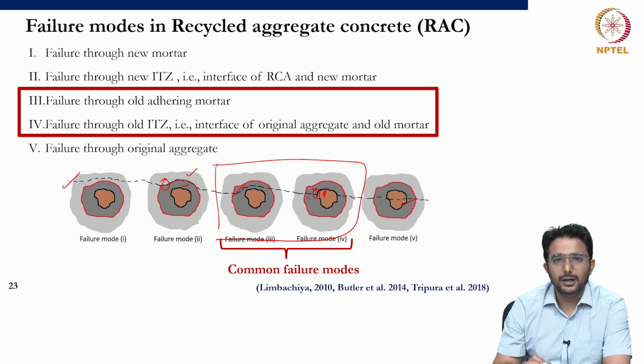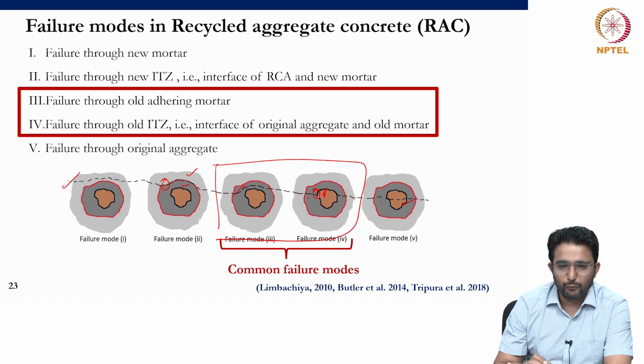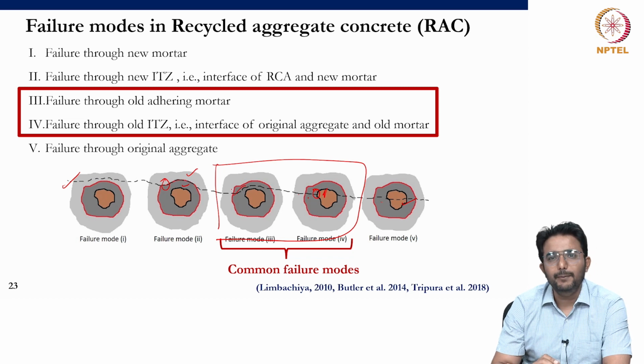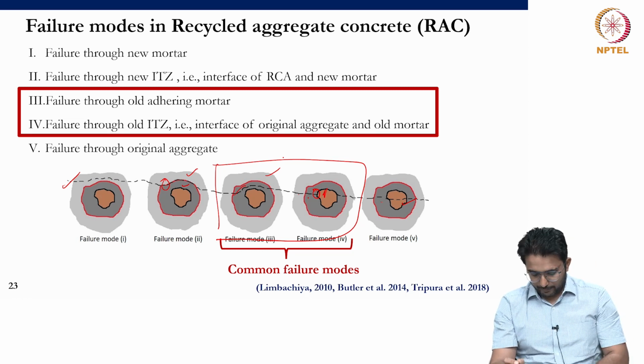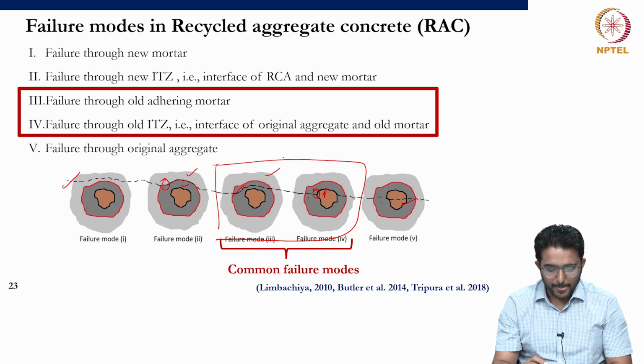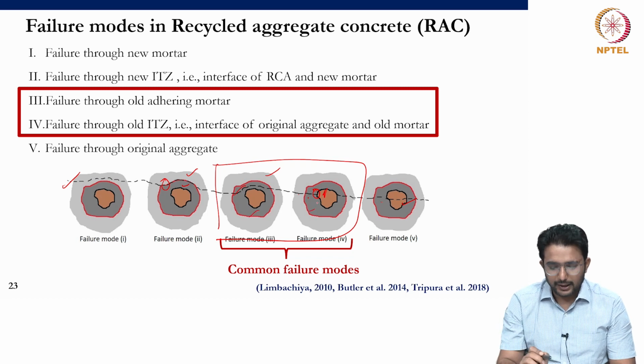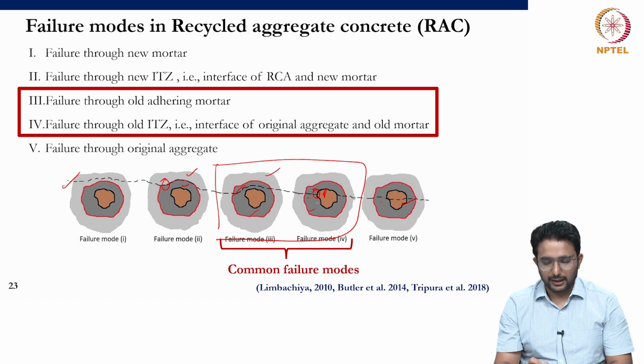So this shows that the quality of the concrete made with recycled concrete aggregate will mostly be dependent on the concentration of the added mortar and not on the new mortar. So that means if you keep on increasing the cement content, the improvement in the strength might not be significant as compared to natural aggregates, right? So that means the added mortar content can be considered as a culprit.